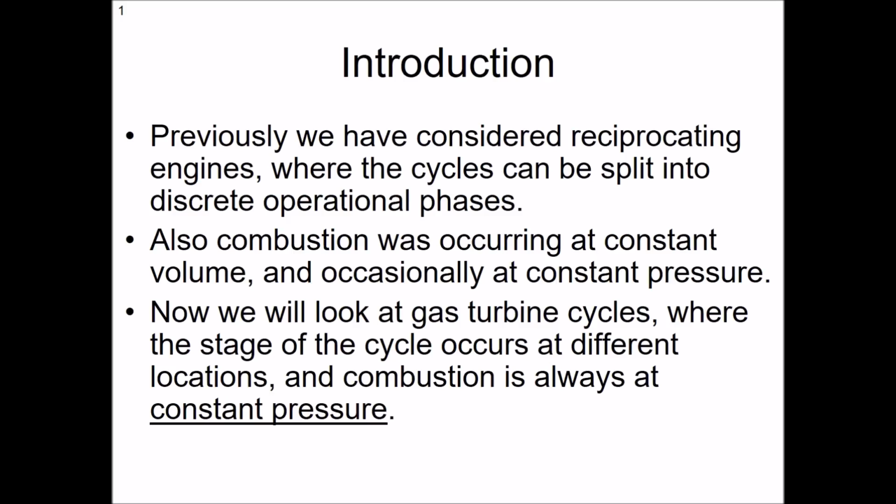That's what we've learned. Now, we're going to do exactly the same thing for the Brayton cycle, but what we'll see is that as some of the heat addition processes are taking place, they're doing so under different conditions. So we take a slightly different methodology for the analysis. In a lot of cases for the reciprocating engines, the combustion or the heat addition is occurring at constant volume, and sometimes it's occurring at constant pressure. But the Brayton cycle works because all of the heat addition is at constant pressure.